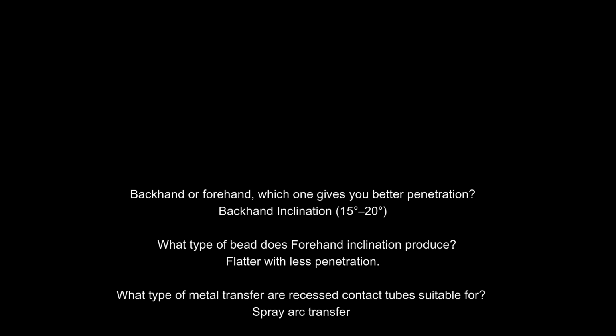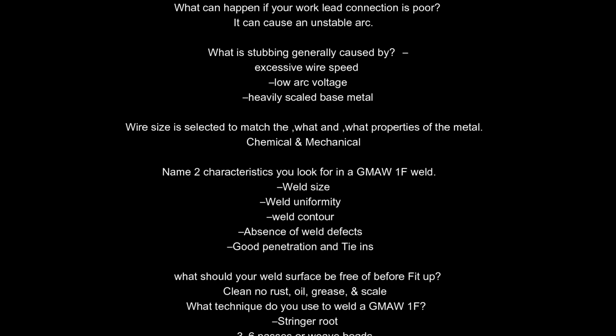Spray arc transfer. What can happen if too much spatter builds up between the nozzle and contact tip? It can cause disruption to the gas flow, and can cause an arc between the nozzle and the contact tip.